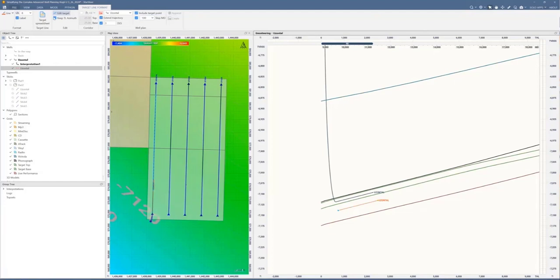It's important to note that the keep TL azimuth here will honor the azimuth of the previous section. So it doesn't matter what I do, move this up or down, forward or backwards, it's going to stay on that same plane. So I'm just going to grab this and extend this green dot out a little bit to right about where that horizontal line is. And I'm going to hit append there as well.